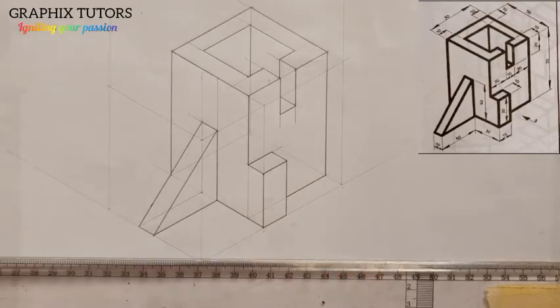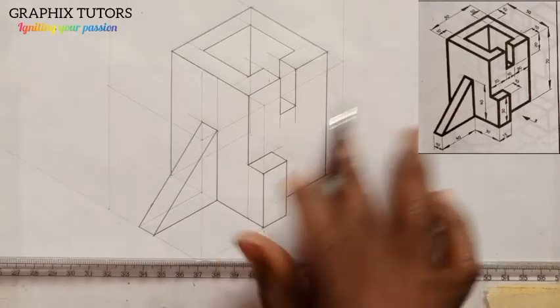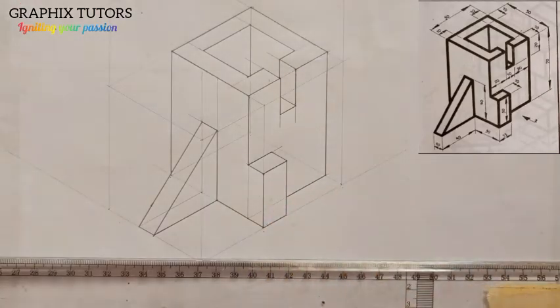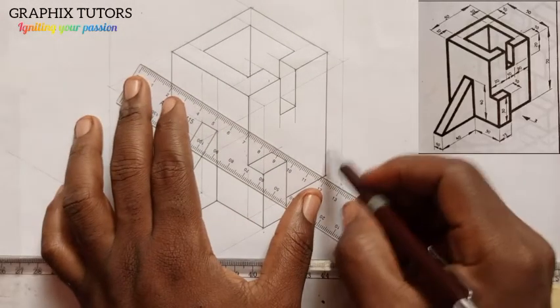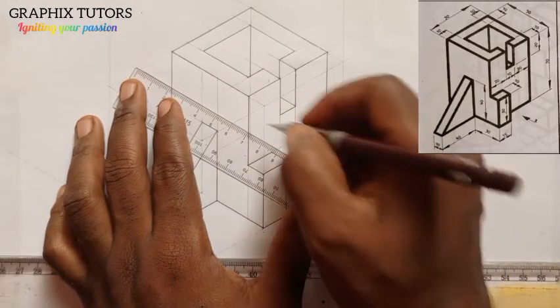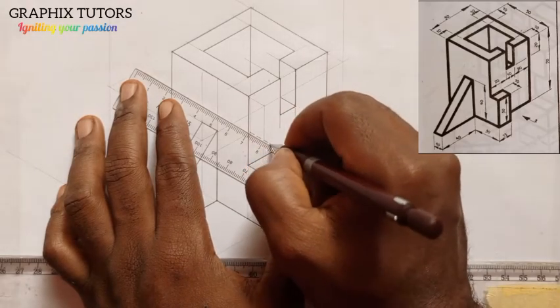Now there are some things that I didn't really bring out here, which are the hidden lines. So let me bring out the hidden lines, which you are not asked to do, just to give you better information on why it's like that. Since all these are faint lines, it means that we cannot see them; the external part of the block is blocking them. So what can we use to replicate them? We're going to use what is called a hidden line. So I'll put my hidden line here, which will give me dash dash dash dash, just like that.